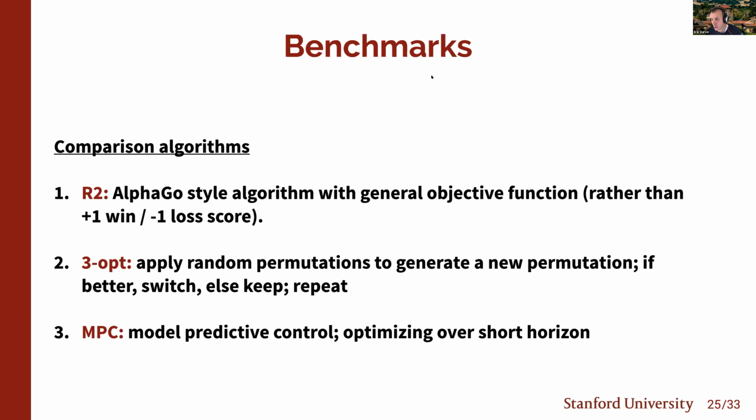There are many methods that are used to improve the quality. But here we're looking at just the laser: by changing the laser path, can we make some improvement? Of course, this can be coupled with other techniques, and people use that to improve the mechanical properties of the part. Another option is to print the same part multiple times and keep the best one, which is often what people actually do.